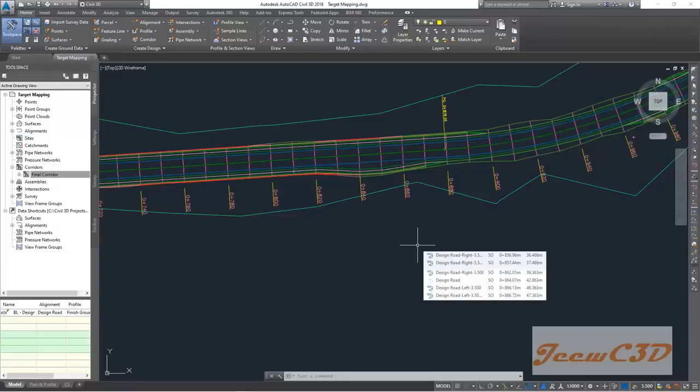You can remember in the start of this section I told you your regions are this both side drain, earth drain, you have this region, then you have concrete drains from this region, then you have bench in this region likewise. So in the next section we will do something called splitting the corridor to have the correct regions.